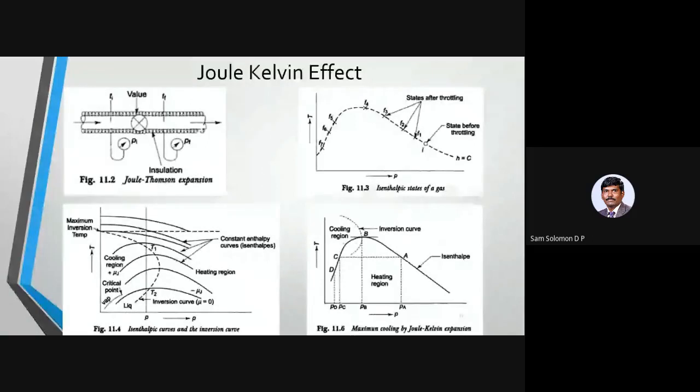This curve which they have depicted, F1 to F7, is an isenthalp. Just like you have a reversible adiabatic line, here you have an isenthalpic line, which means along this line enthalpy is constant. But it does not represent a throttling process, which means I am not representing an initial value 1 and a final value 2, and I am not drawing a process 1, 2.